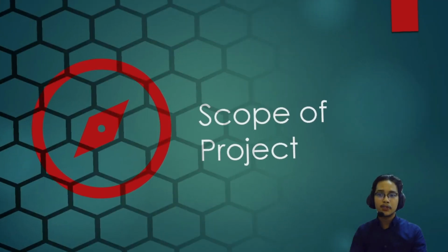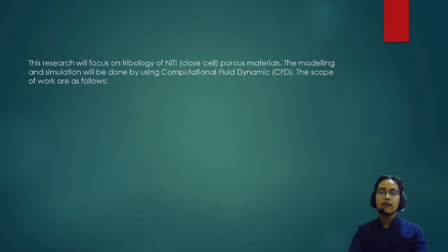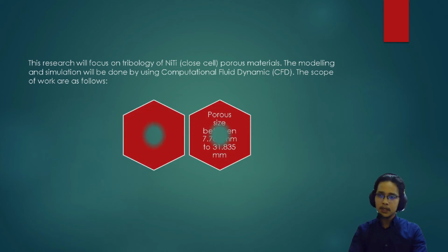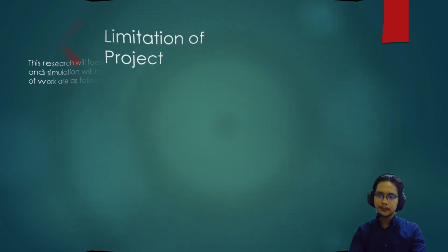Now, the scope of the project. This research will focus on the tribology of nickel titanium closed cell porous materials. The modeling and simulation will be done using computational fluid dynamics. The scope of work is as follows. The first one, throughout this project, the pore size is between 7.787 mm to 31.835 mm. Second, the arrangement of pores is randomly distributed.